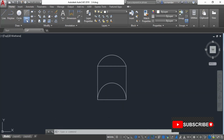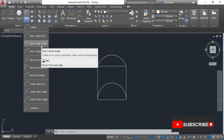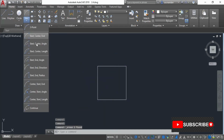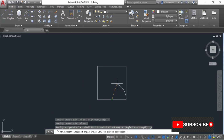Now let's go to the other option here, and here we have this start, center and angle. Now before making this arc, I'll simply erase both of these arcs which we have made, and now select this start, center and angle. So once again, we need to first click on the start point, then the center point, and now the angle. Now this will be the included angle of the arc.